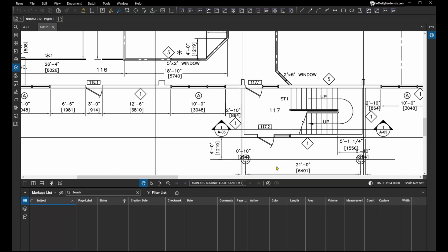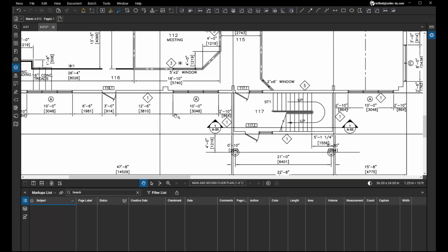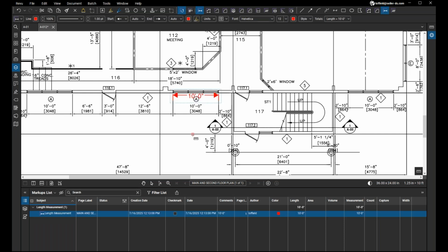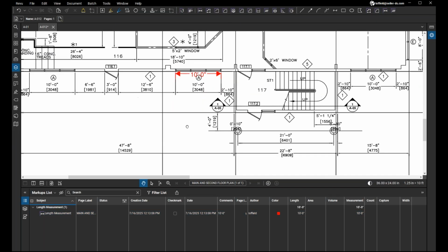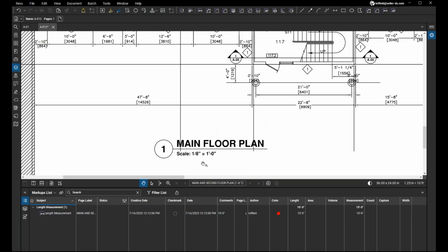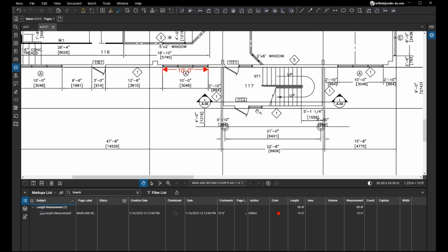Then I'll click apply scale, and we have that scale applied. Now we know that any measurements we apply from that point on should be accurate based upon the measurements that we gave it. So if you're ever in doubt about that, sometimes the scale is provided, sometimes it's not, but we have other things that we can make use of.